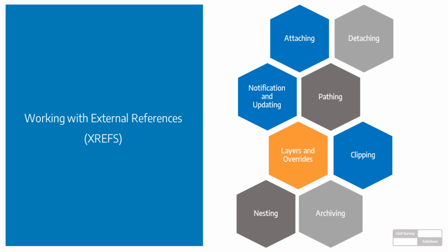We'll also have a look at nesting external references. So we might have a layout plan that's got references for the electricals, for the drainage and all that sort of stuff in there. And we may have a master drawing, and we bring that layout plan into our current drawing, and you'll find that all the nested Xrefs will come through under certain conditions. And then we'll have a look at archiving, and that involves binding the Xref into your drawing, choosing how it gets bound into our drawing, and how we can manage network locations and things like that.